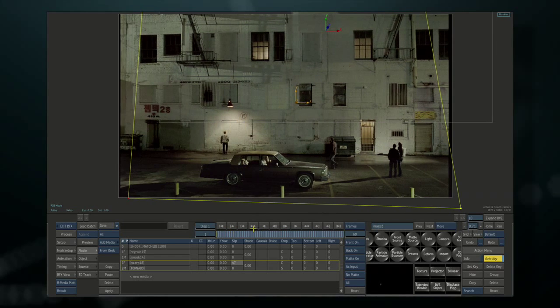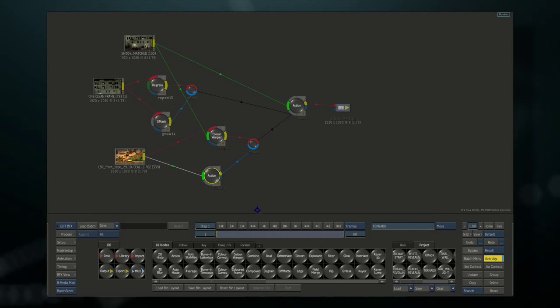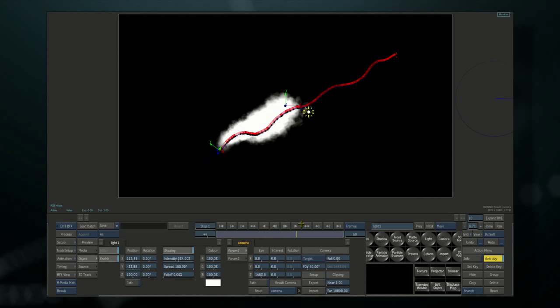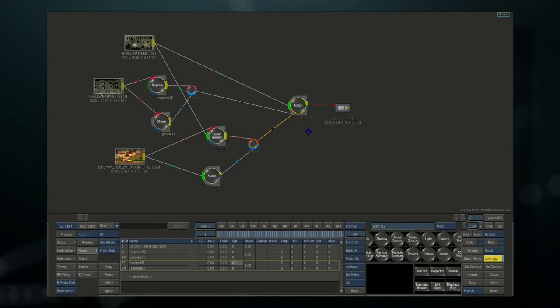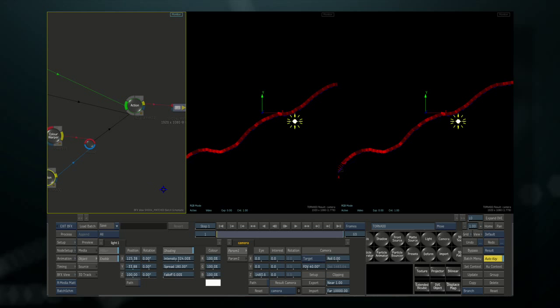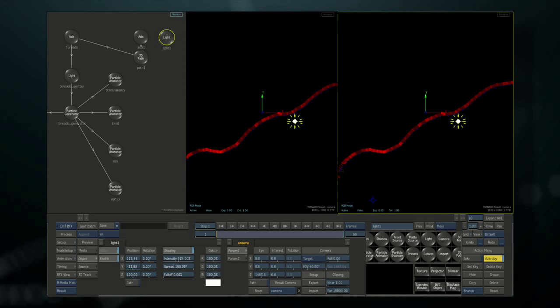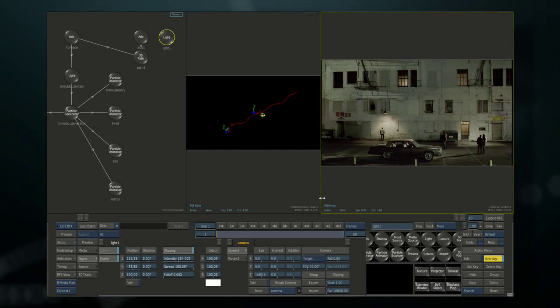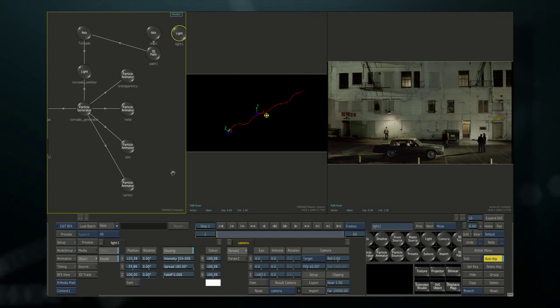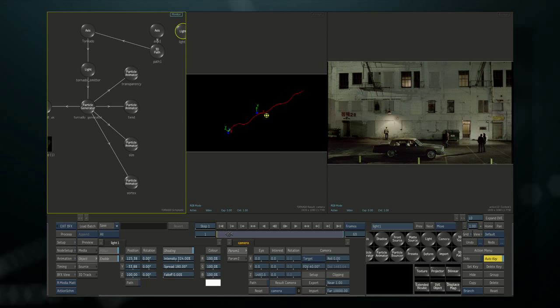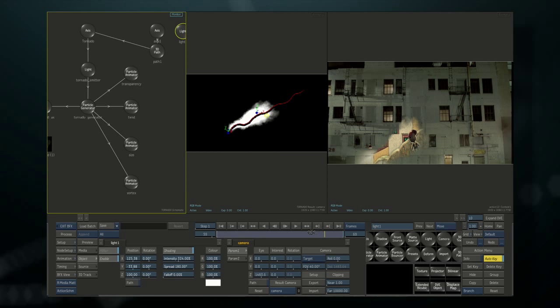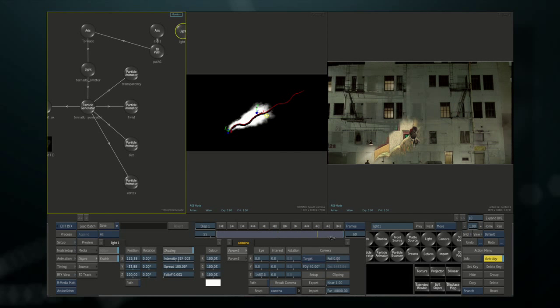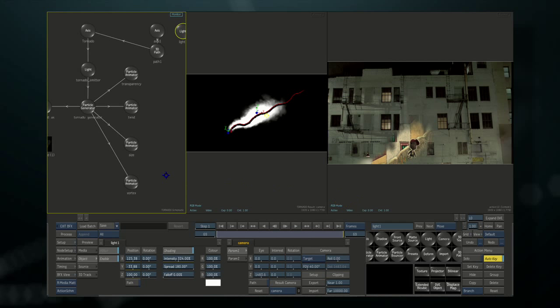And again, this brings up another really good thing about doing procedural compositing. I want to affect what's going on down here in this particular matte that I'm creating, but I need to see what's going on up here. So let's go ahead and set a context. When I split the views, and we'll do that three ways, what we're going to end up with is, on the right, our context view showing our final composite. On the left I have the schematic of the previous action, and in the middle I have the result of that stage of development of our matte. So this is what's great about procedural compositing. I can be working upstream from the final composite.